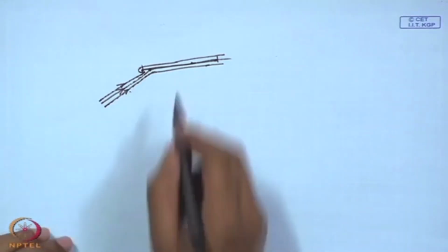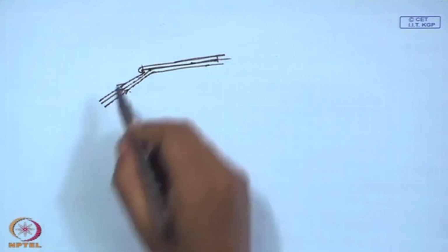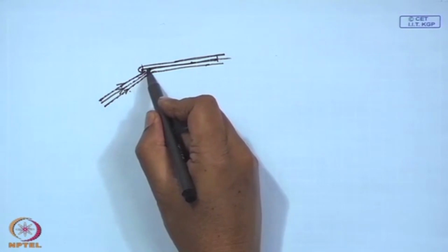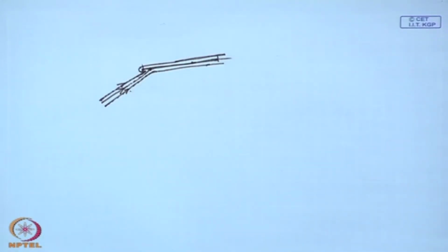So, these are the streamlines, flow streamlines, or the flow will be like this. The inviscid potential flow about a flat plate airfoil will be like this. This streamline will go here and then will turn back and go round over the upper surface. What is the velocity at the leading edge? Can you find out what will be the velocity at the leading edge?